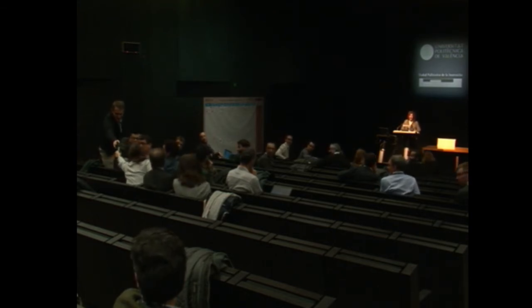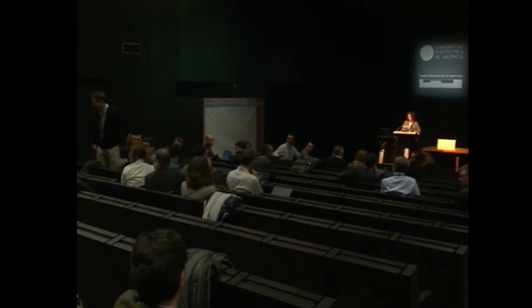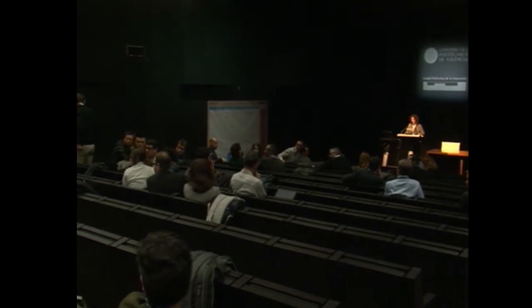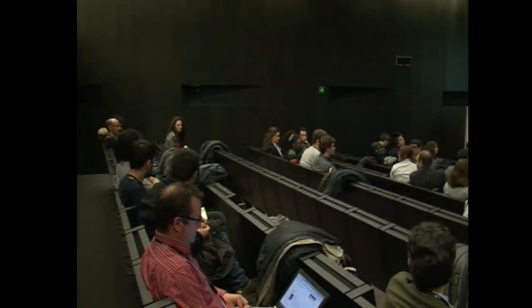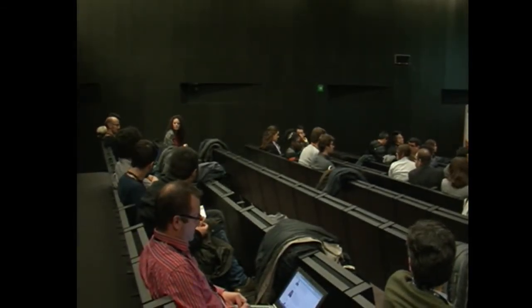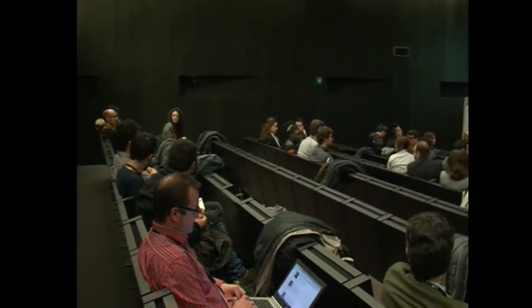Okay. These are thermal tuners. So it's a metal on top that you inject a current into, and it heats the waveguide. So it changes its properties, basically the refractive index. So if you put it in a Mach-Zehnder, for instance, you will switch it. Or in a ring, you will move the resonance. So that's it. It's to change the refractive index locally.